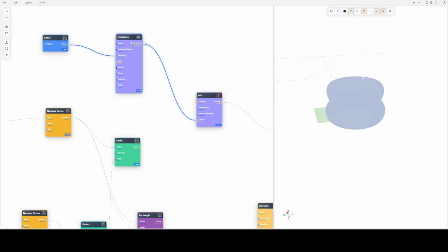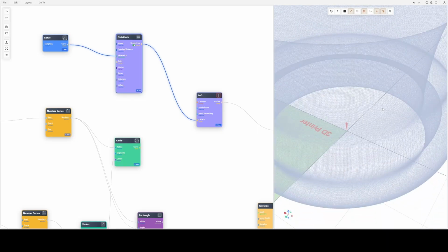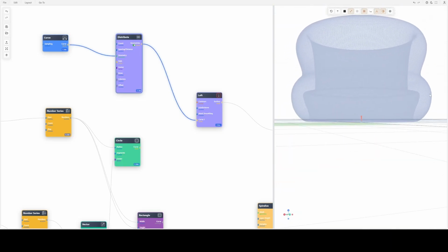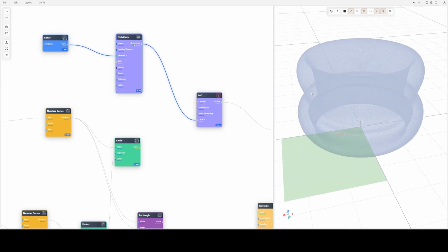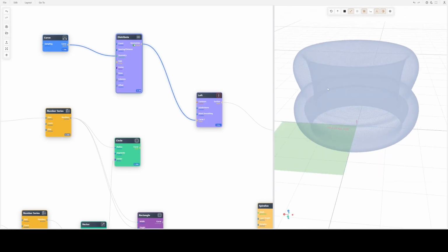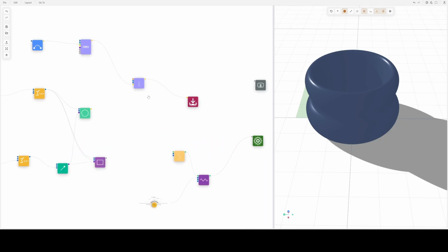And you see, if you look into that, it's a very fine mesh, and it's a closed mesh. So you can download it as STL, and then you can print it as solid volume with infill. So it's not just outer wall. This was the loft.